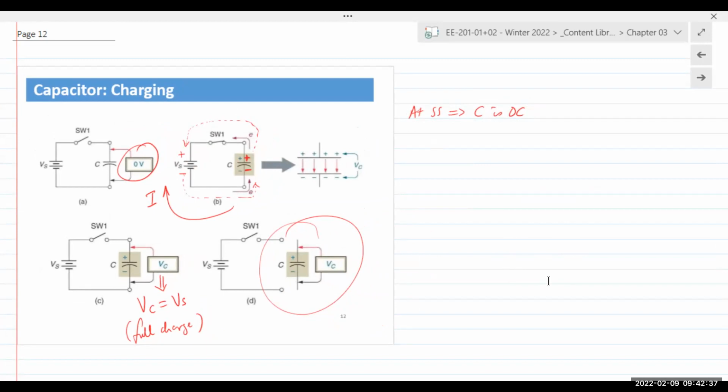Okay, no matter how good of an insulator you have, you can represent it as a finite resistance. That resistance could be hundreds of mega ohms, which for all intents and purposes is infinity. Yet real life insulators and real life capacitors will have some finite amount of resistance. That resistance will allow a certain amount of current flow.